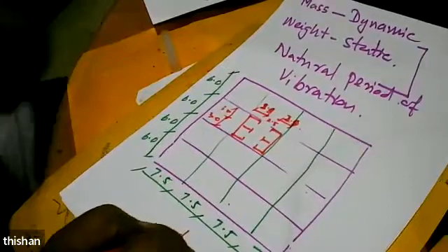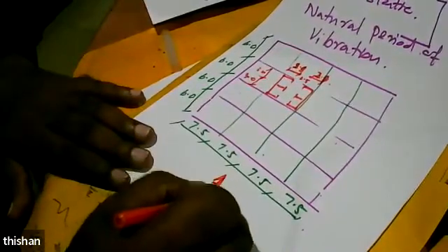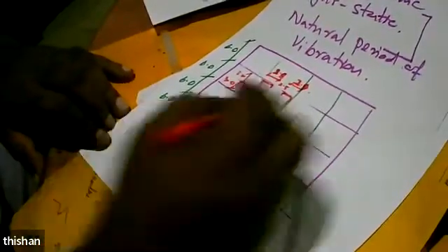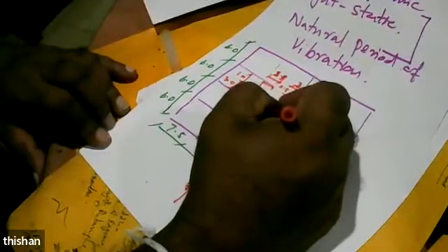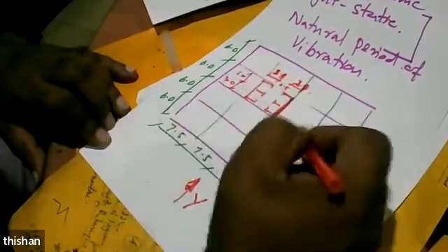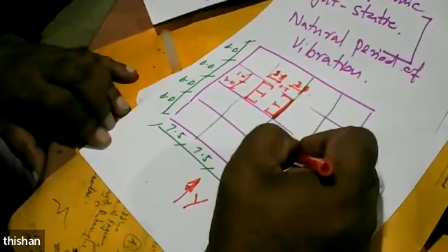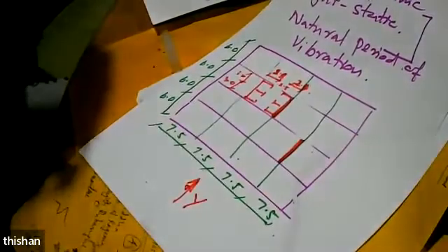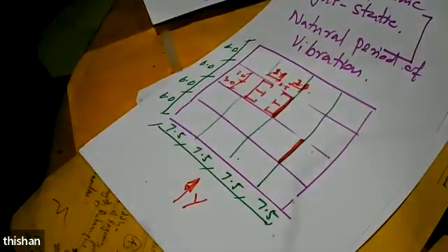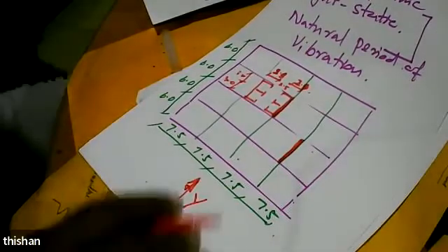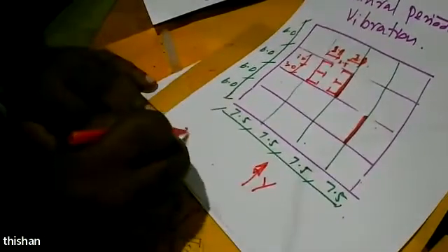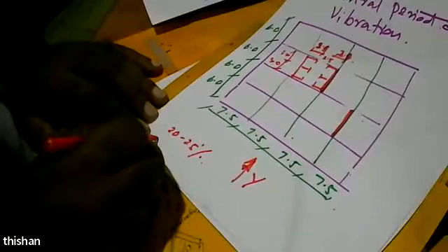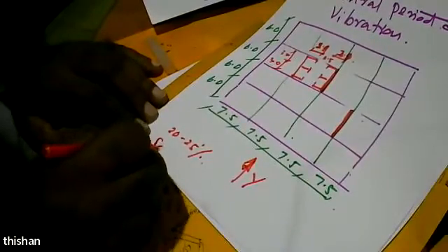And if you have considered wind in this direction, that is the y direction wind, this is not good. Why? This wall is almost on the y direction center, but there is only one wall. So to balance that wall, we need another wall here. Then you'll ask, can you provide concrete walls like that? Answer is yes. Because generally, we expect 20 to 25% of the building to be services.